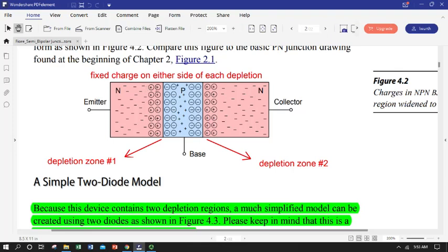So we've diffused some pentavalent N-type dopants into this material, and we probably already had some trivalent P-type dopants in our P section. So we already had some positive charge carriers in our P region and negative charge carriers in our N region, and as you probably remember, at the interface, those recombine naturally in the material and annihilate, and so we've got a region of intrinsic semiconducting material right in here,